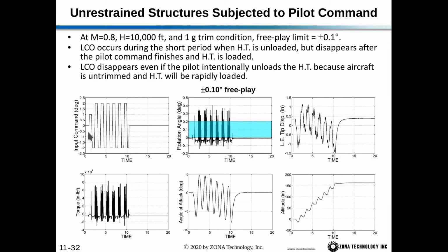So this is our input command. So you can see that as we transition through these regions where the horizontal tail becomes unloaded, we develop an LCO response. After the pilot stops yanking the stick back and forth, the LCO disappears. And even in these short time periods where the horizontal tail becomes loaded, you can see the LCO quickly disappears.